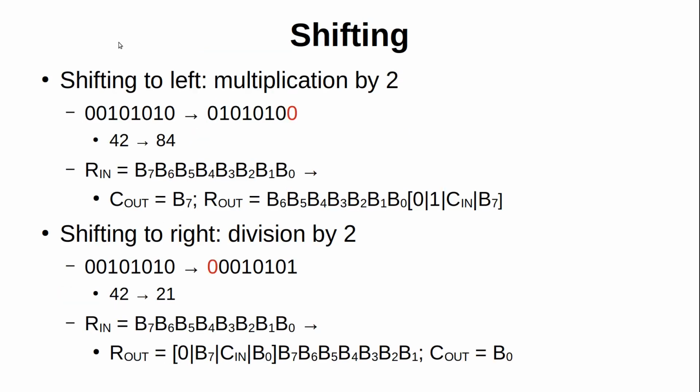Another bit operation we have already seen is shifting, which comes in handy for fast multiplication or division by powers of 2. But there are many other cases where we want to move bits around in lockstep. Bitwise shift instructions on the Z80 only operate on a single byte at a time, which means that when the bits are shifted to the left or right, the other end needs to be filled in with a new bit value.